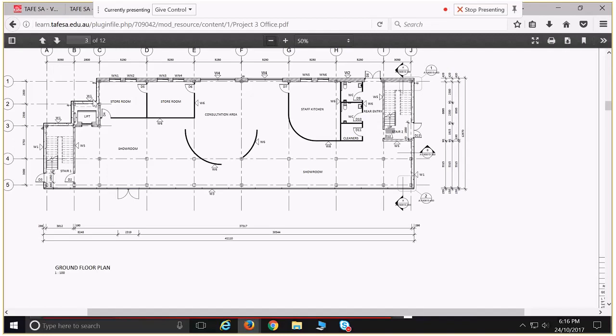With this floor plan, through every structural element, so we have the end walls, end wall A, B, and C, we have a grid line for those. And then we have dimensions for the center points of those walls that creates our grid. Other important structural elements are our columns. We have column center points in line with grid line C, center points of these columns in line with grid line D, and so on, all the way through.